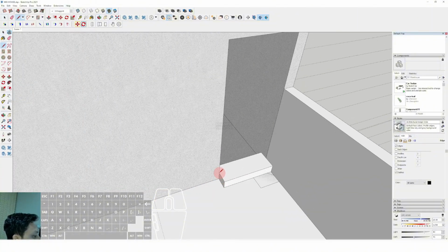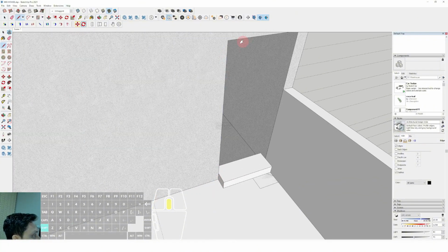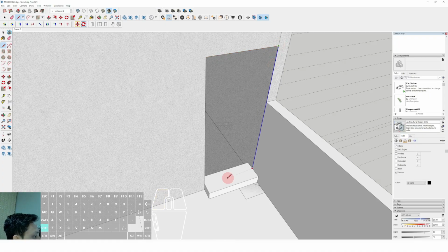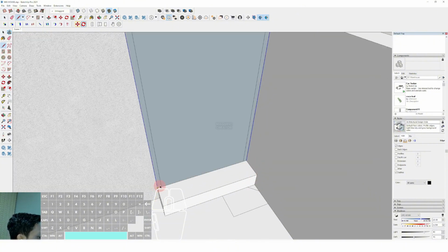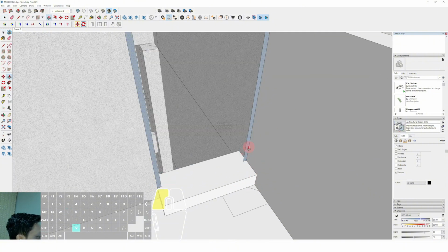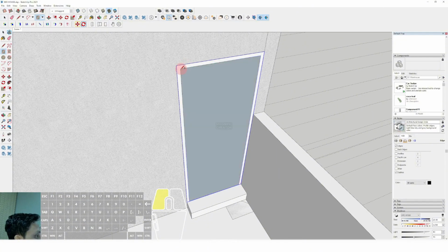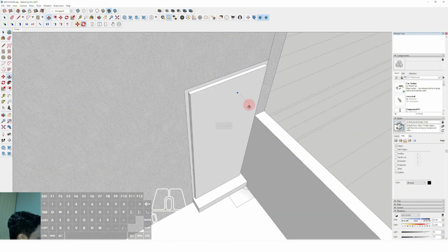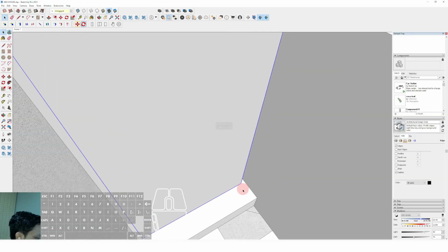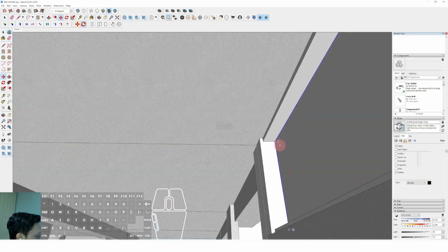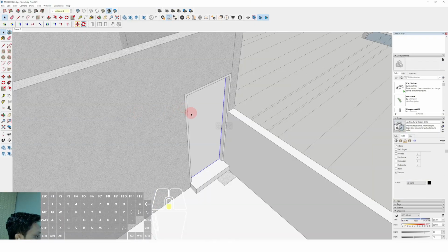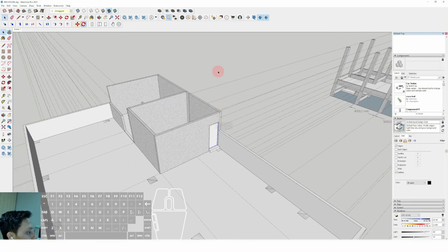Okay, we can make the simple drawer element first. Can triple click, offset 35 for the aluminum frame over there, erase, and push it to the behind 120. Triple click, make group, and make the rectangle, and push it to the front 35, enter, make group. Then now we can move it to the behind like this. It's done for the rooftop.